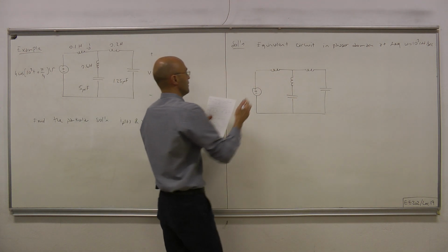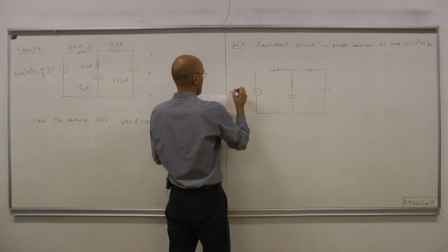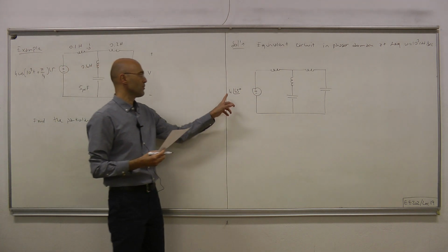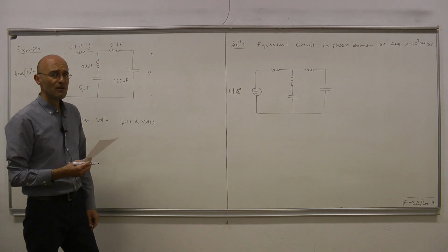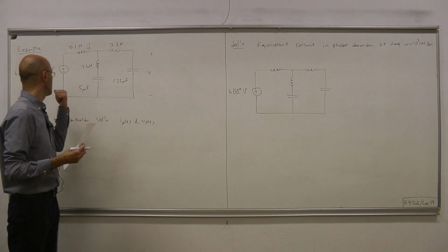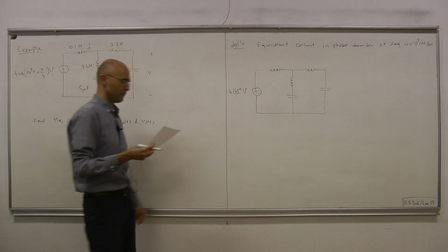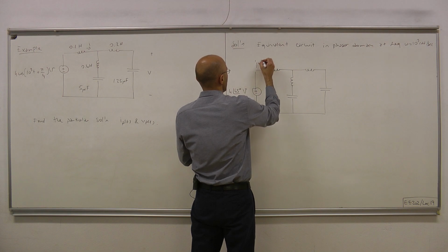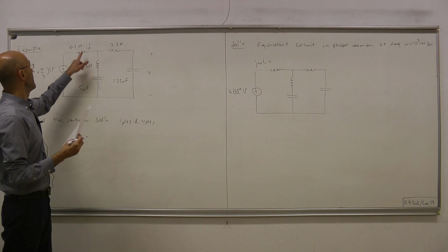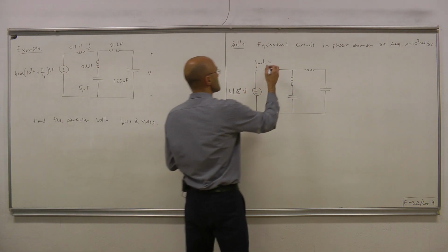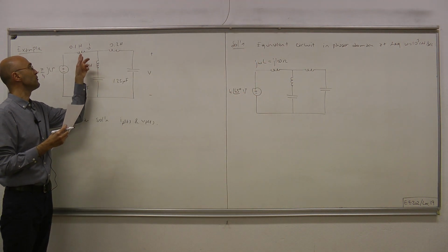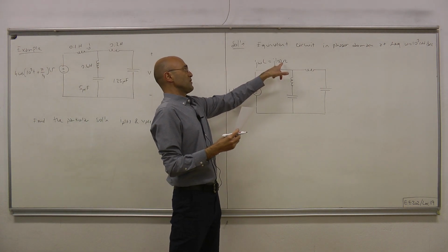Here we have, first of all, the phasor representation of our input, a complex number with magnitude 4 and phase 45 degrees. Unit is the same as unit in time domain, which is volts. Here we have J omega L for the impedance of our inductor. Omega is 1000, L is 0.1, so this makes J 100, units is ohms. So henries are transformed into ohms.